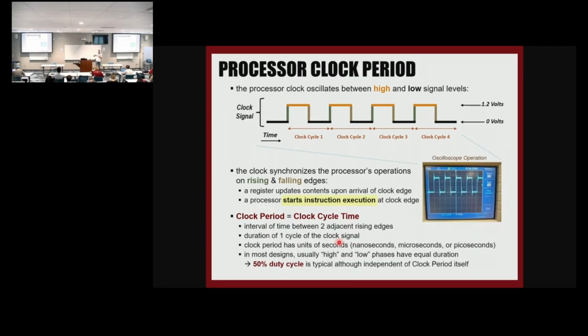So you can actually have multiple types of clocks. You can have a base clock, and from that you can create different clocks for different parts of your circuit. So you have a design and you want to have different speeds in your design, so you can generate the clock from the original clock, and then you can tune the duty cycle based on your application. Again, I'm mentioning these things now just for you to have some idea when you hopefully do some SystemVerilog coding. But when we say do this in positive edge of the clock, you have some idea about the synchronization, right? Any questions so far?